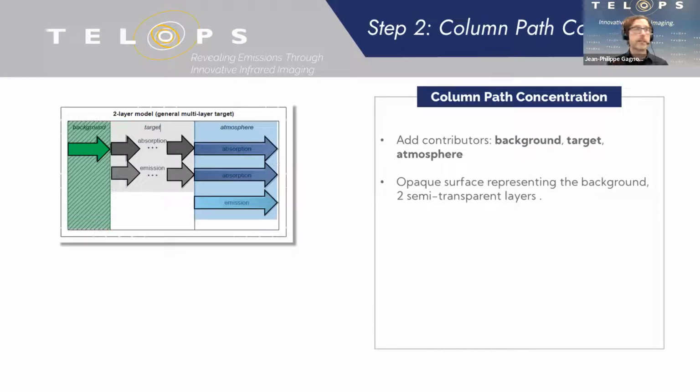But basically what we build here is we make ourselves a little model of the scene, composed of the different layers that the camera measures. So basically every layer is responsible for producing infrared energy that ultimately reaches the camera. So the first layer is what we call the background. So the background is whatever lies behind the gas plume that we're trying to measure, such as solid objects. So this could be a building, trees, the blue sky. So this is what we call the background.